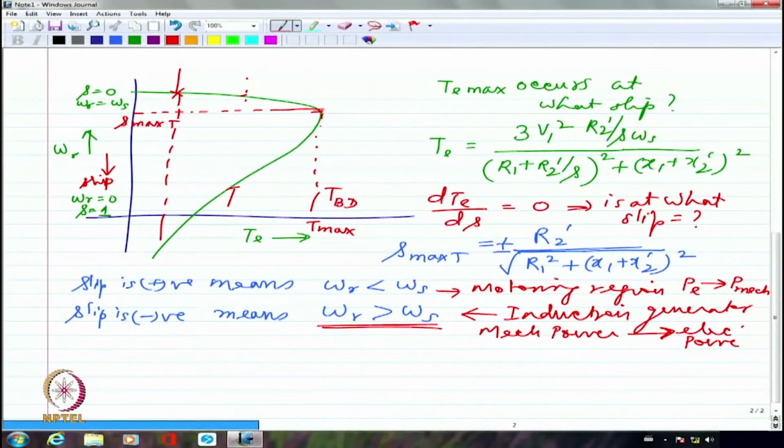If I have a constant torque load, for example, let us say an elevator driven by an induction motor. So 8 of us have gotten in. Maybe the torque corresponds to some value like this. It is starting from 0 speed, clearly. So unless I have some amount of torque in excess, there is no way acceleration will take place.